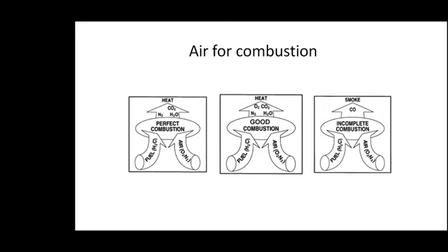As we said earlier, if combustion is incomplete, it results in carbon monoxide. So there is also a loss. But if too much air is given, there is no carbon monoxide, but the excess air that you are providing for combustion also takes away a lot of heat. That is also a loss. So there is an optimization that is going to take place.